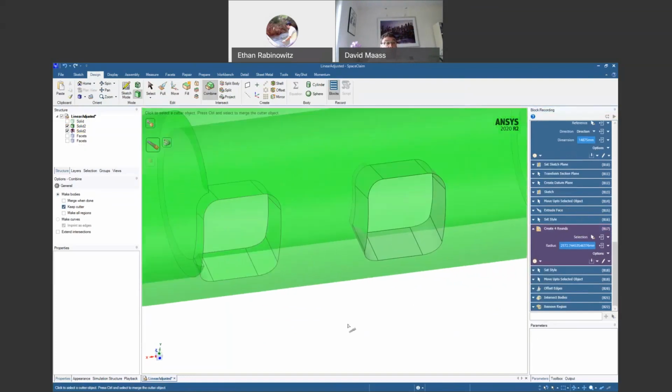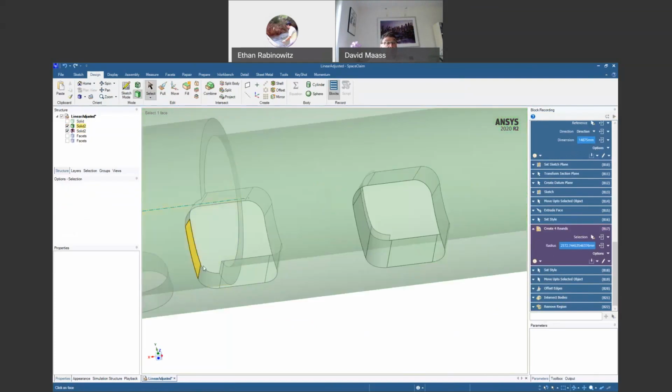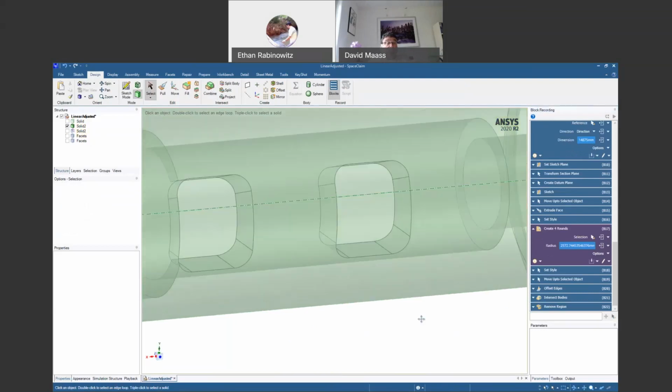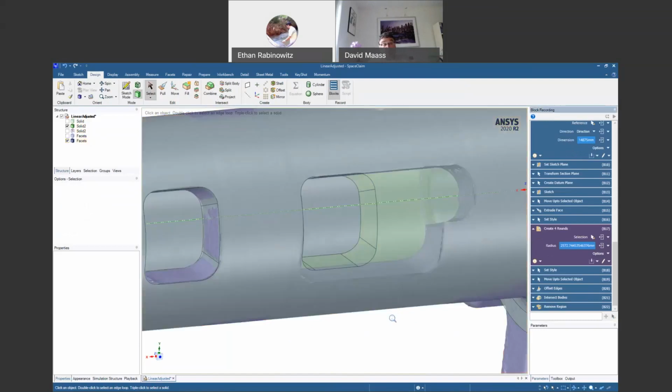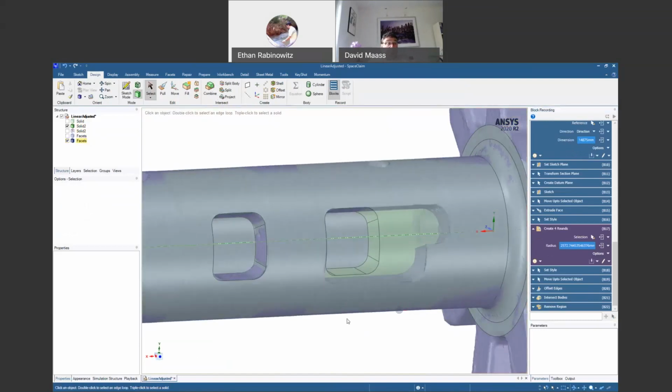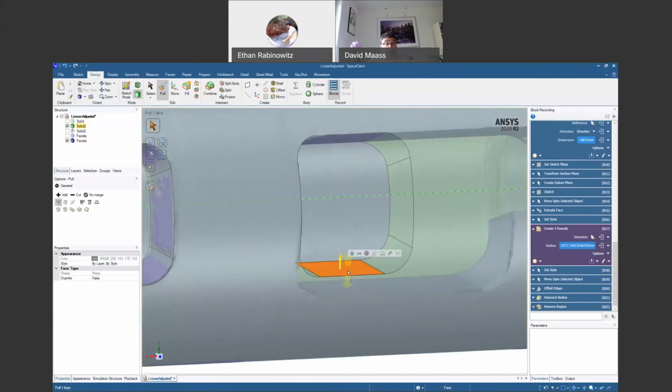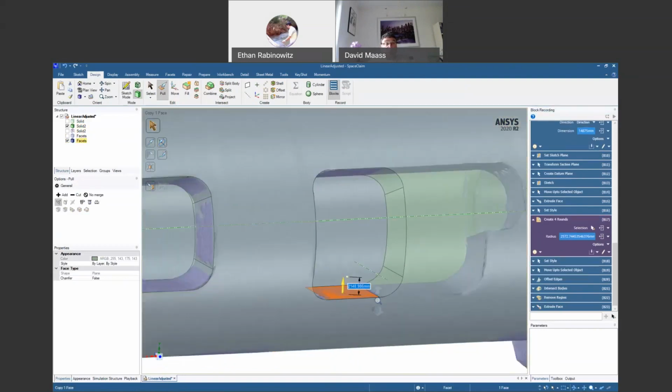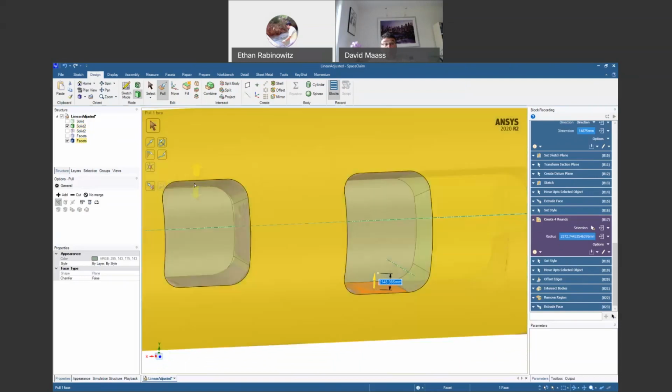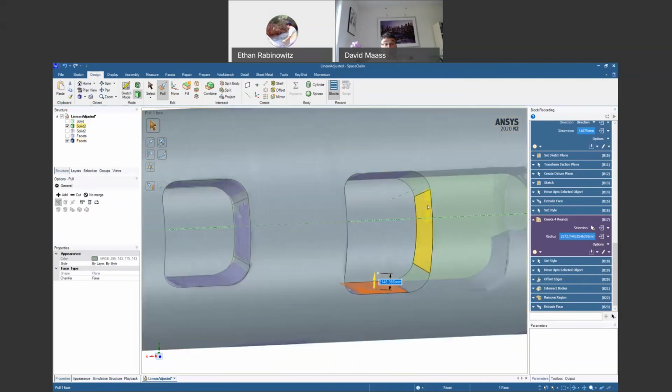So it kind of just threw the copy for a loop that there was this cutout here. It wasn't able to figure it out, but with a quick adjustment on the copy it made, we're able to then use that copy to subtract it out. So now we've got that and this. We're deciding that it's parallel, so we'll say pull up to, pick a face down there like that. And since this was just copied off of this, if we go back and edit any of the dimensions on this one, those will get copied into this one.